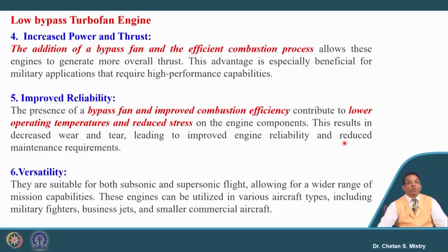temperatures, the stress, wear and tear of the engine is reduced, and that has improved the reliability of the engine. That has given more permeability to use such engines for aero applications, and they are more versatile both in terms of subsonic operation as well as supersonic operation. That is the reason why such engines have application for fighters, business jets and smaller commercial aircraft.